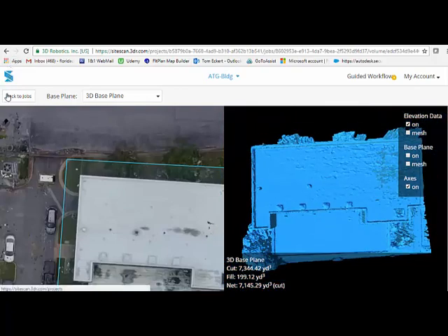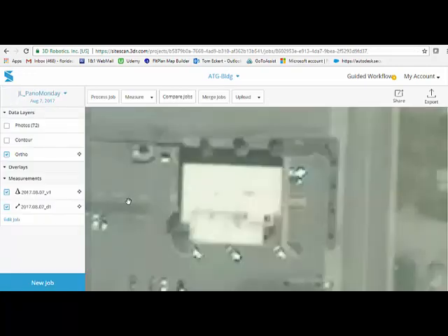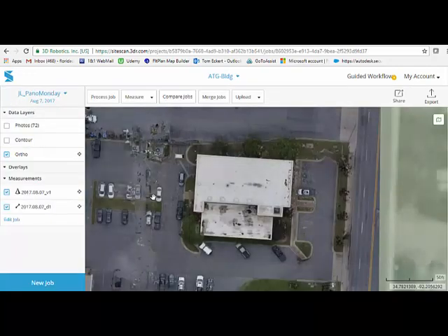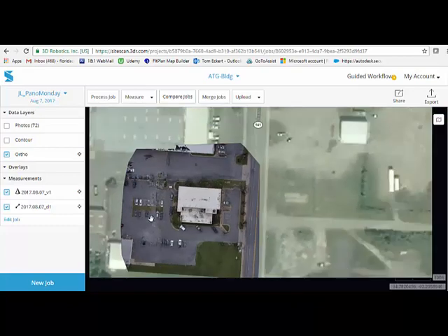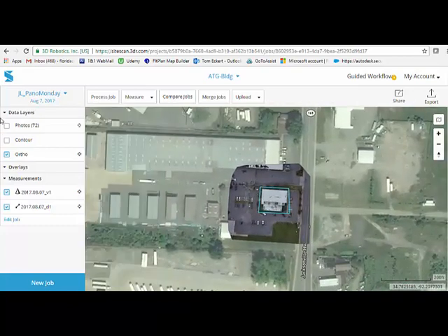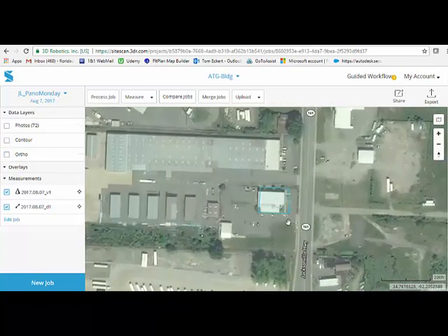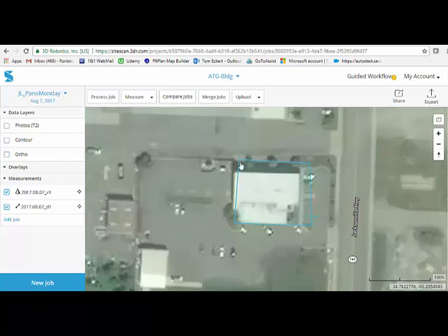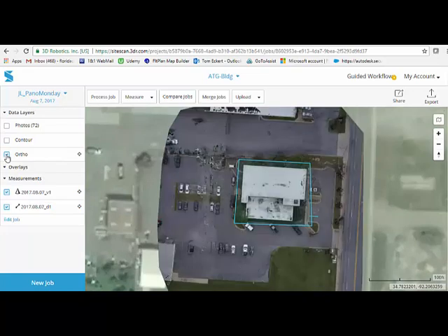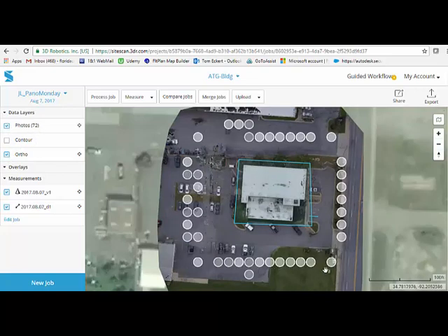So let's talk about some of the metrics on this job. Flight time. We set up on the site. We're standing right over here. Here's the ortho mosaic. We spent 5 minutes mission planning on a situational awareness. Then we put the drone up in the air. It took 72 images here, flying 2 elevations. Each one took 4.5 minutes. So you're looking at a 9-minute flight to get an entire 3D model at that point.